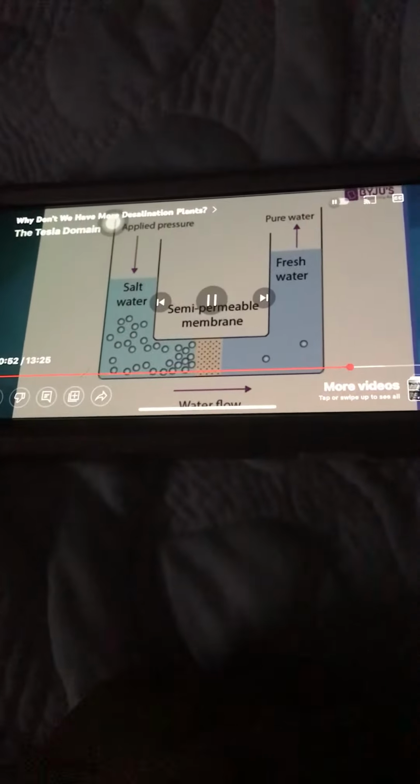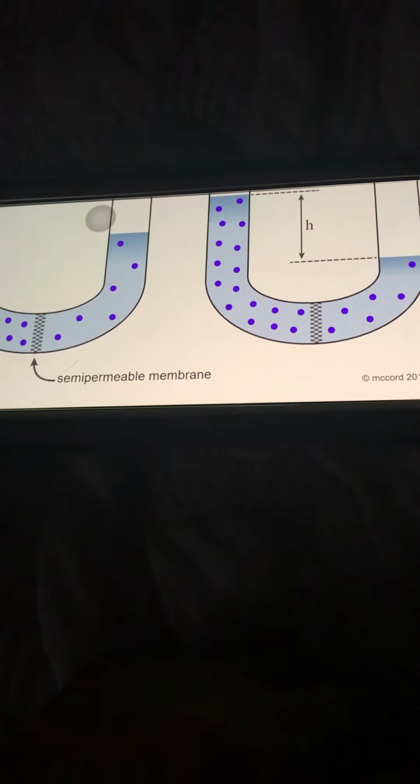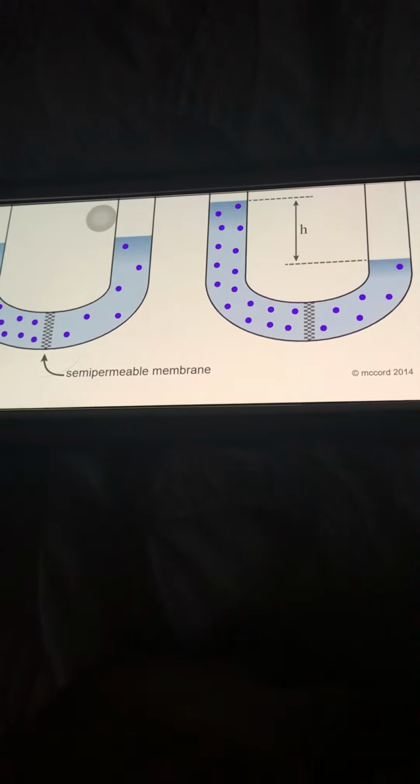In a concentric spiral pattern that allows alternating feed water layers and spacing of the brine, RO membrane, and the porous product, the aqueous carrier. The product's porous water carrier allows makeup water to flow through the center of the membrane element to collect in the product waterline. The individual membrane elements are connected in series so that each pressure vessel can process more water.